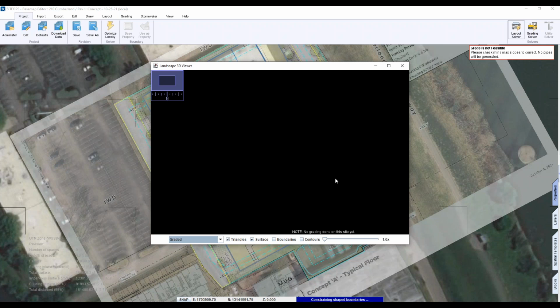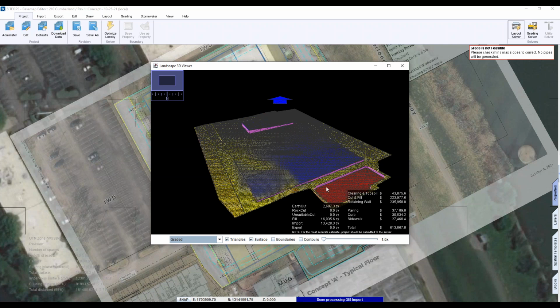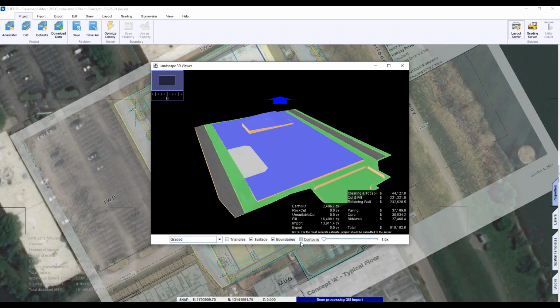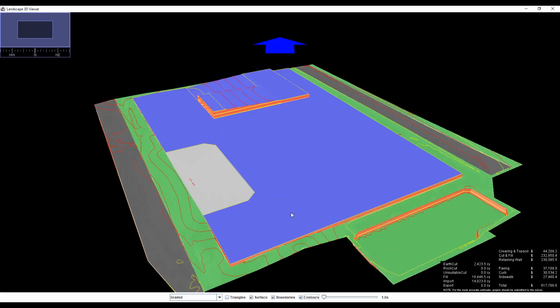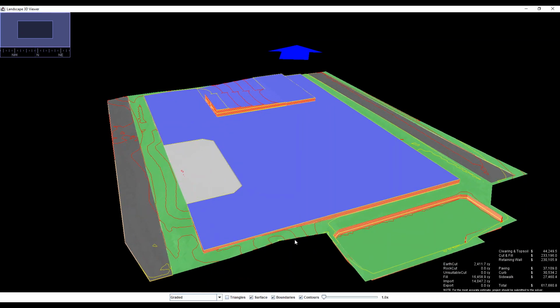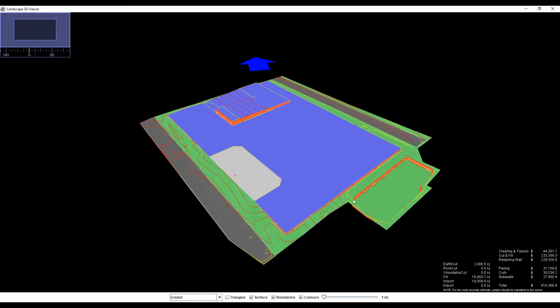I was just going to clarify, we switched files here into one where we had pulled in topography outside of the webinar, so now we're acting on existing ESRI terrain. This one has all the stuff in it, with some extra things that I drew in there. We have a stormwater basin over here. It's a very small basin, so we put walls in to make it work.